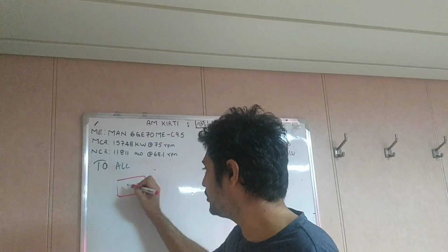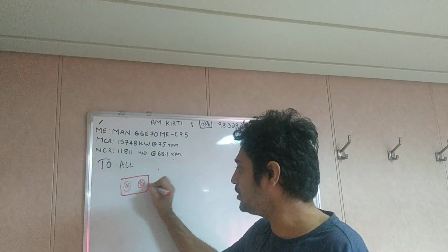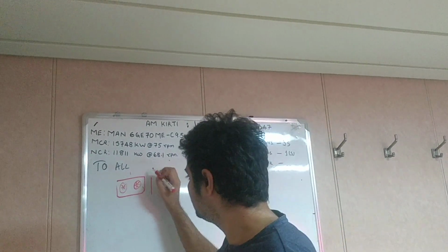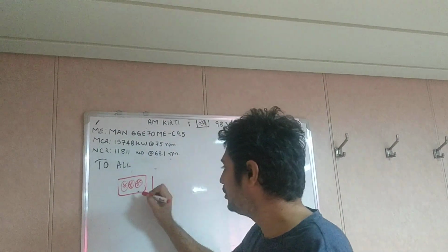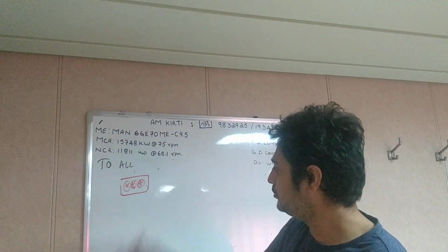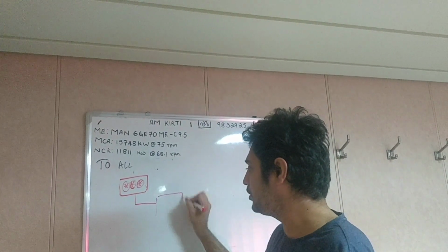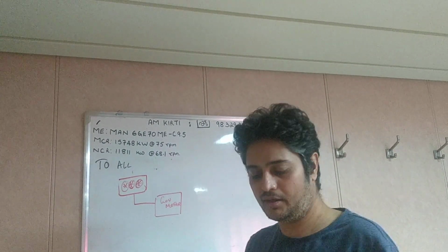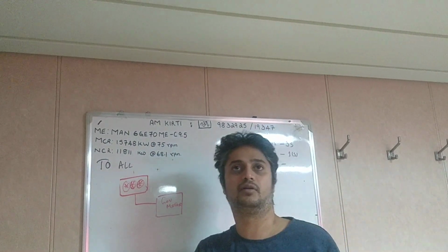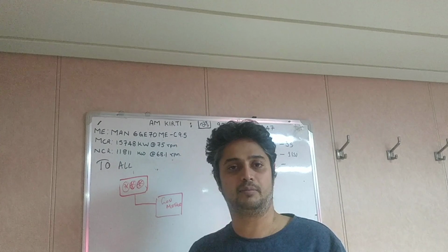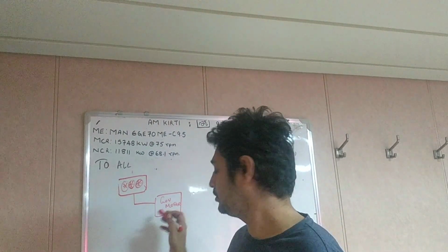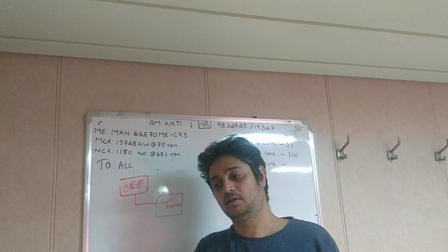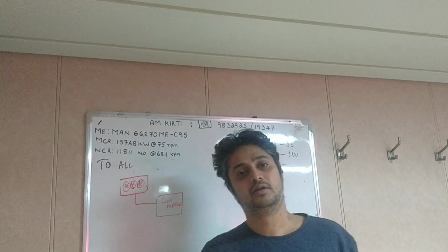What it is doing is, suppose there is an increase or decrease for one, this will give a signal to the governor motor. When two generators are running and one high load kicks in, this is what will happen. Both the governors have checked the drop in the RPM and then they have increased the fuel.